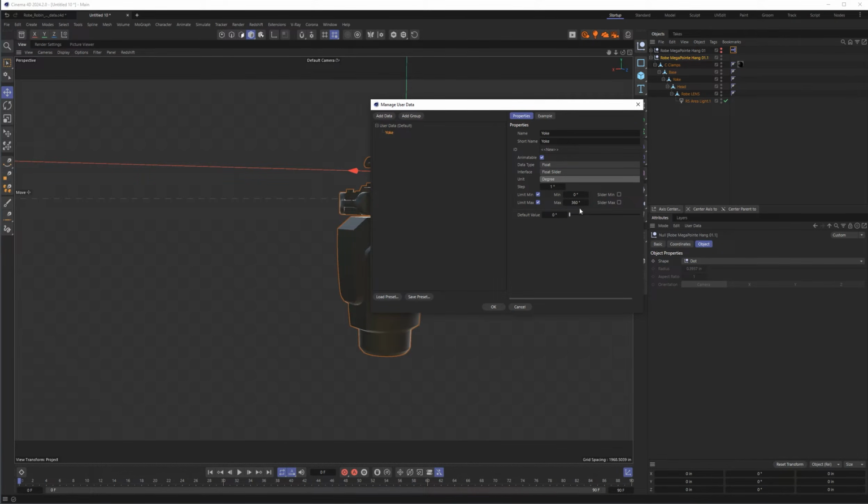So we'll start there. The default value of where it's going to start is 0, so that's good. And then the steps are just what degrees you want in between the movements as you move it up. So you could up this if you wanted to rotate only in 10-degree increments. You could set it up that way, but we'll leave this just like it is.